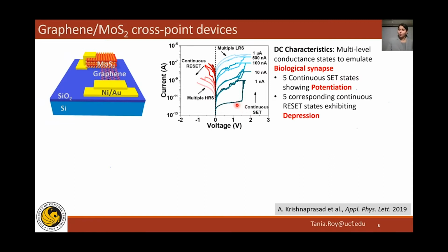We have a very low off current and reasonably low on current here. The operating currents are in low microampere ranges, in contrast to, say, oxide-based systems where the off current will be nanoamperes or microamperes, and the on current will be in the milliampere ranges. So low operating current was a positive.